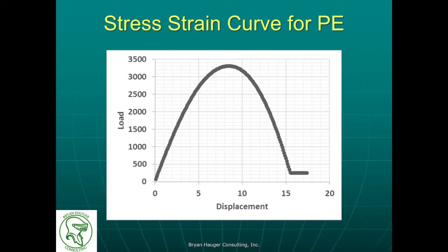Then the load starts to decrease as the cross-section in the yielded region thins. If this is a high-density polyethylene, perhaps we'll see the yield stress somewhere between 3,000 psi and 4,000 psi, and a yield somewhere between 8% and 10% strain. Continuing to strain past yield, we obtain some type of an arch shape before reaching the bottom of the arch, and there is a flat or nearly flat region at the bottom illustrating the drawing of polyethylene. Many of us stop there, but some continue further.